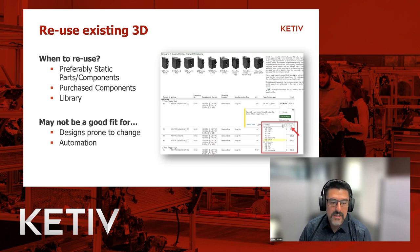So again, not a good fit for things that maybe change. If they can be swapped out, that's one thing. But if you're downloading a part or an assembly and you want to stretch it, that's typically not yours, right? Or maybe it doesn't have information that lends itself towards it, and of course automation as well. So be careful with that. If you're going to automate some of this, take a careful look as to, is it going to stay static within the automation, or are you planning to stretch it, change it in a number of ways?